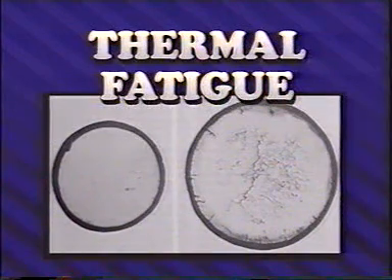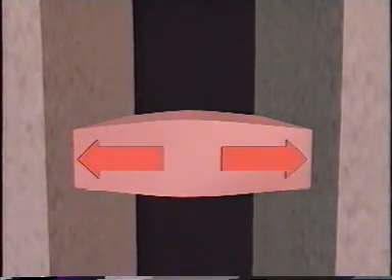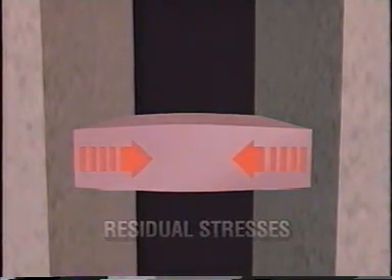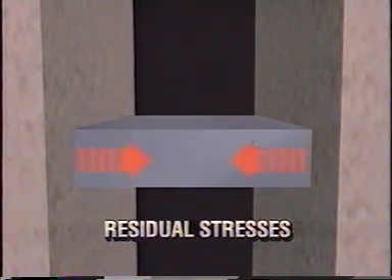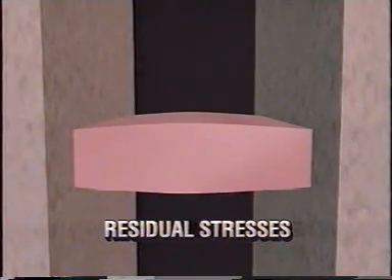Thermal fatigue is a residual stress effect. It is caused by simultaneous mechanical restraint and repetitive thermal changes. The thermal expansion is caused by a local temperature increase. The expansion acts against a restraint, usually the harder, stronger, cooler metal adjacent to the heated metal. When hot, compressive yielding may result, and during cooling, the compressive yielding, in turn, causes tensile residual stresses from the thermal contraction. Repetitive thermal cycling can result in fatigue crack formation and propagation each time the metal cools to the lower temperature.